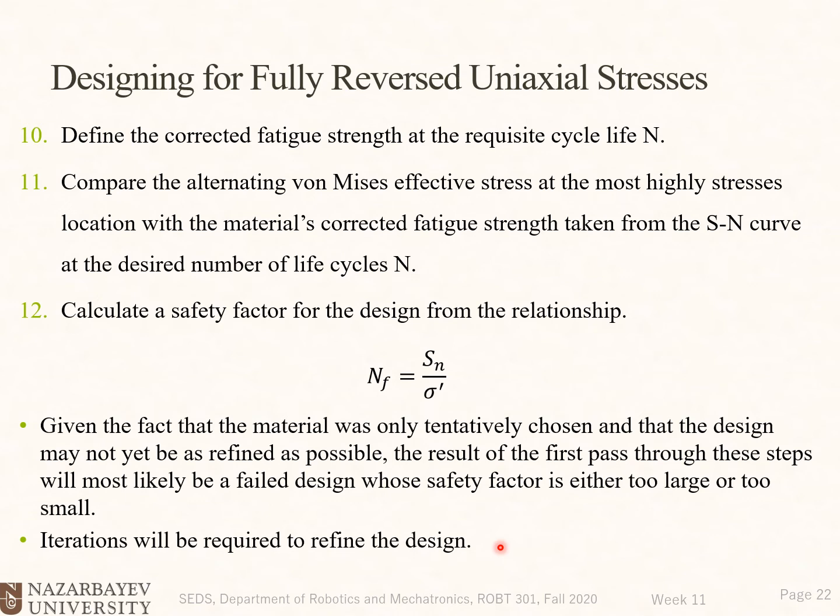And if we play with those and change them, then we could end up having a nice safety factor, something that makes sense. A safety factor of 2 or 3 is desired, or maximum 5, depending on the number of uncertainties in the engineering model.